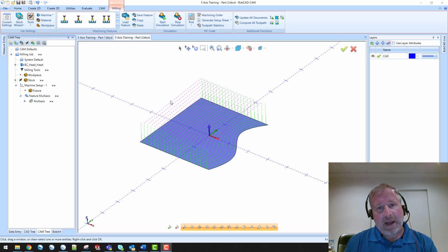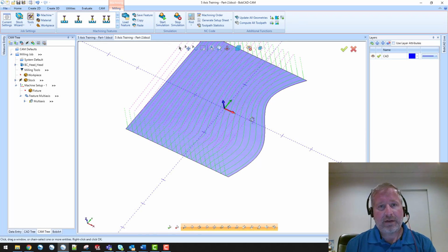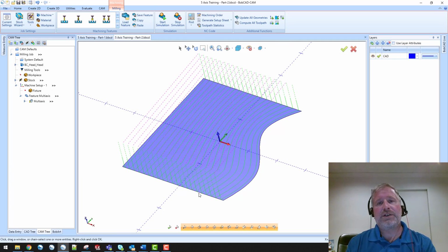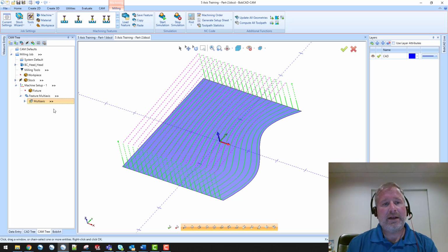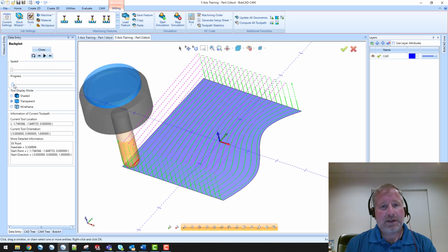So on the screen now I have a rectangular surface where, from the top view, I simply took a spline and cut that edge so we can see the same tool path. We've got one straight edge, we've got this curved edge, and that is what's actually going to change our tool path. So creating the same multi-axis morph between two curves,